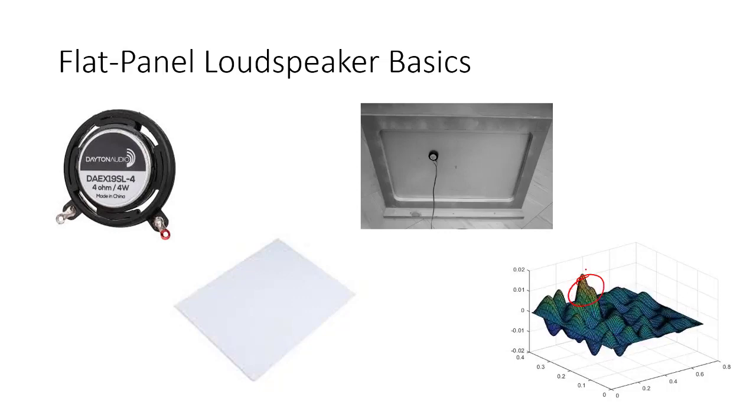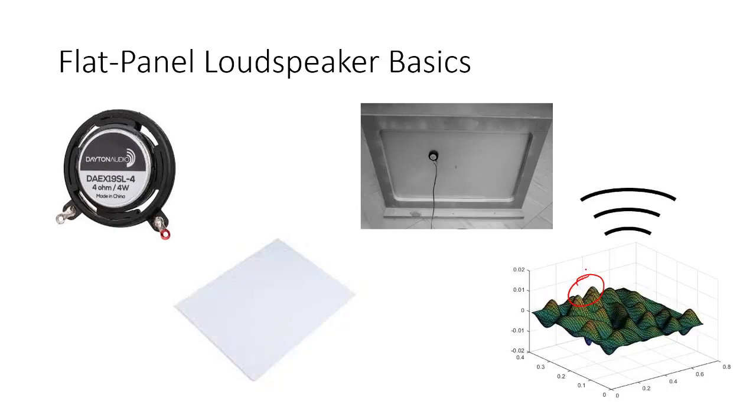But anything that vibrates is going to produce sound. So the vibrations mechanically are going to actually radiate sound into the air. It's pretty tough to mechanically configure these flat panel loudspeakers to give good sounding radiation, and so that's what I spent a lot of time researching and working on. One of the key aspects to doing this is just being able to pick the panel materials correctly in order to give something that doesn't sound terrible, and that's what I'm going to focus on right now.